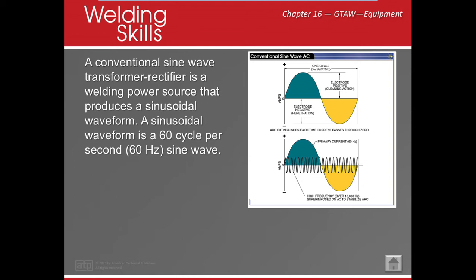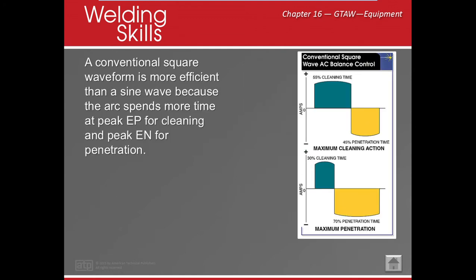Okay, so we need to know that electrode positive is the cleaning portion. Electrode negative is the penetration. Okay, so here comes technology that changes everything. Next thing up, well, square wave. Well, you guessed it, it makes square waves.